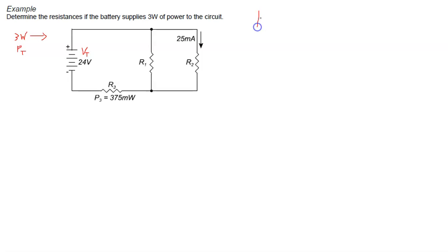And if we're bringing in the power, power is equal to I times V. And of course, we know that we can make that I squared R or V squared over R. And if we think about Ohm's law then as well, with these two equations or combinations thereof, we can, with two pieces of information about any resistor or the circuit, find the other two pieces of information about any resistor or circuit as long as we apply our formulas correctly.